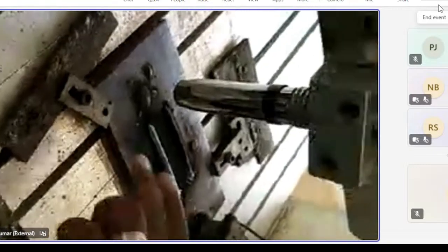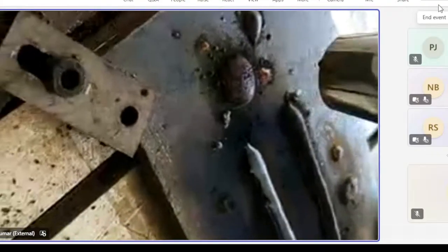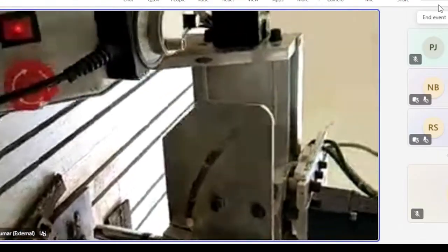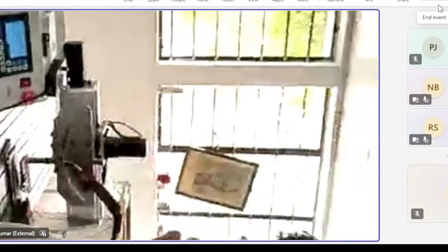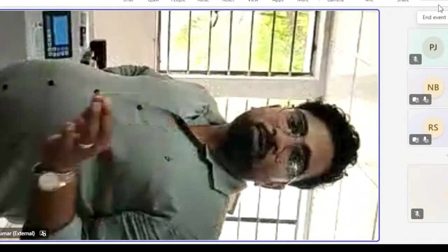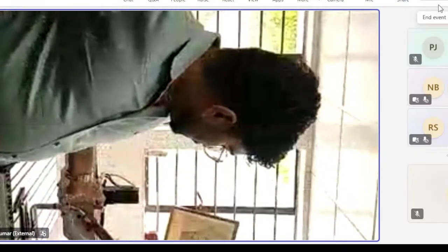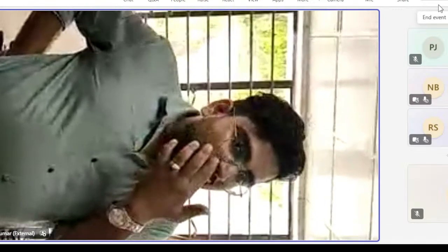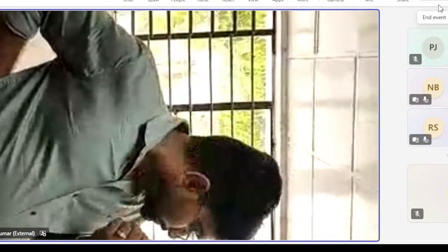Experimentally, here some black carbon is also visible. This is due to some lack of gas flow rate. If we increase the gas flow rate, this can also be encountered. Although the important part, I want to add, is that to get a proper bead and proper deposition, the first thing is that the environment is very impactful. So cleaning your substrate plate is a very important part. Otherwise, there are chances of some defects in the deposition.